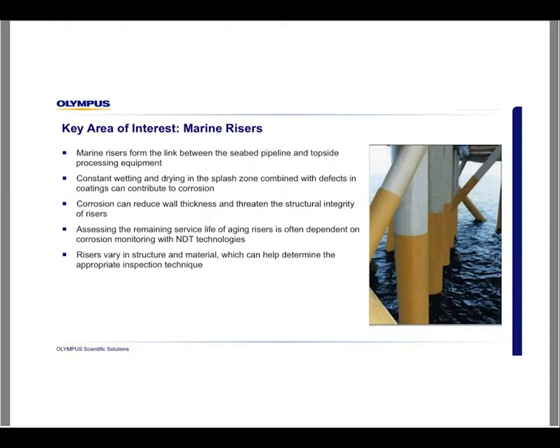Marine risers form the link between the seabed pipeline and topside processing equipment. The reason why this is such a key area for corrosion is that the risers are in what is called the splash zone, which is the area of the platform that's right above water level. So there's constant wetting and drying, and this combined with potential defects in coatings on the risers can contribute to corrosion.